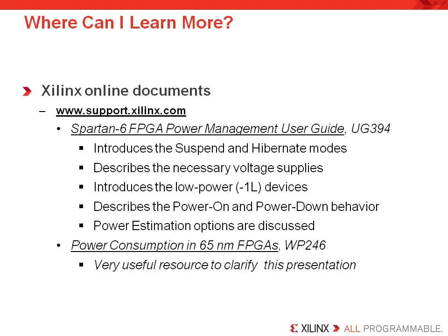There are lots of places to learn more about FPGA power consumption, and they all start at support.xilinx.com, but we do want to mention a couple of things that are very useful to you. The Spartan-6 FPGA Power Management User Guide, UG394, is very helpful to understand some of the power management features that are included in the Virtex-6 and Spartan-6 devices. Note, there is not an equivalent document for Virtex-6. Check this one out, though. Also, be aware of power consumption in the new 65nm FPGAs by reviewing white paper 246. I think you'll find both of those very helpful.